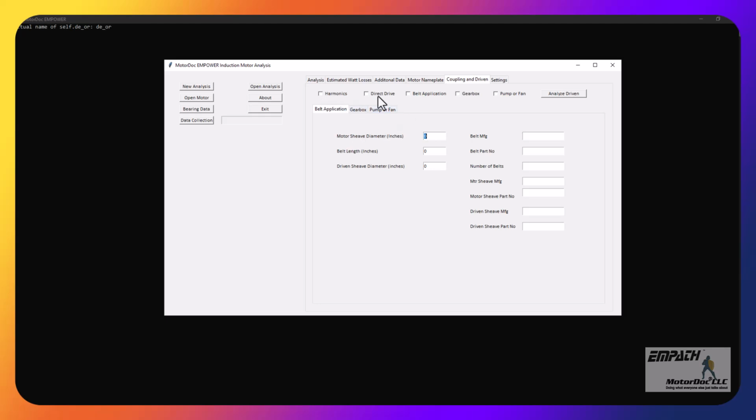And then up here, all the different analysis selections, you can select more than one. The harmonics one in particular also includes supra harmonics, or harmonics over 50 orders, and interharmonics out to 22 kilohertz.